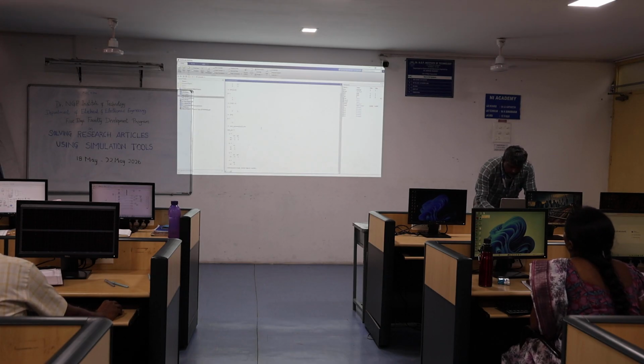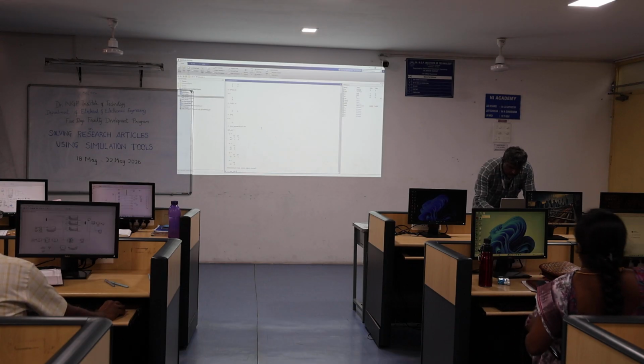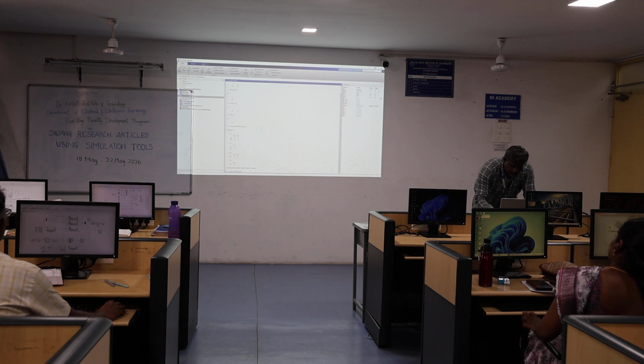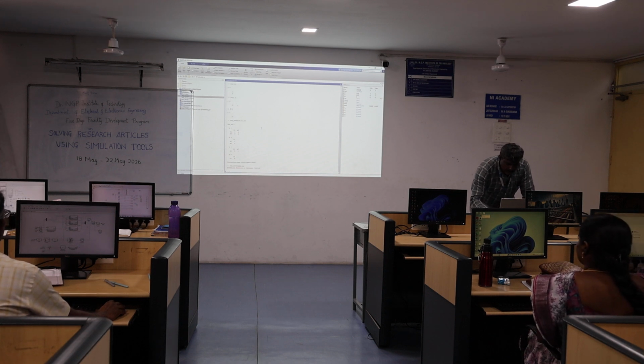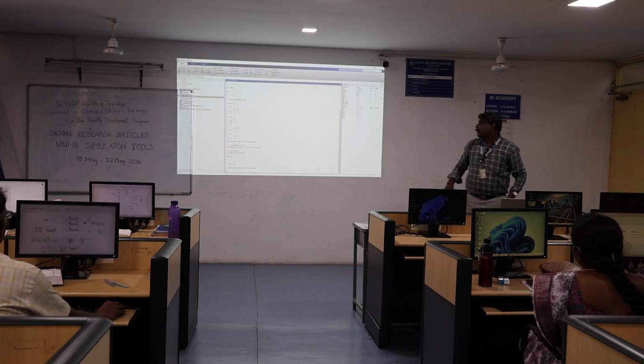So let us take SYS transfer TF is equal to TF of SYS-SS, then enter. So you will get the transfer function, right?